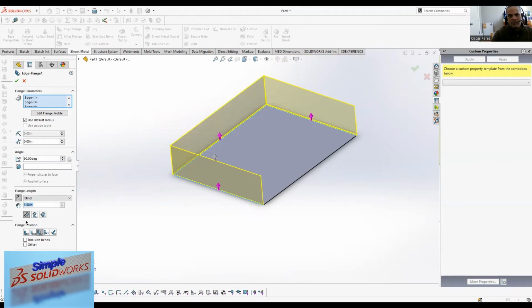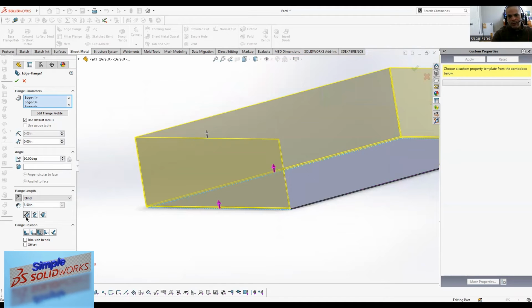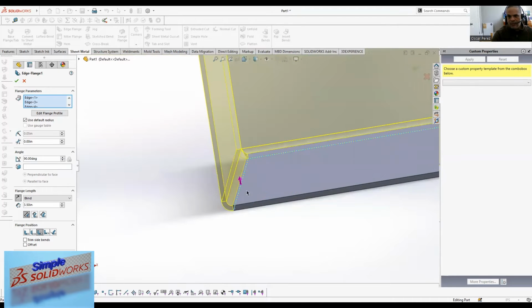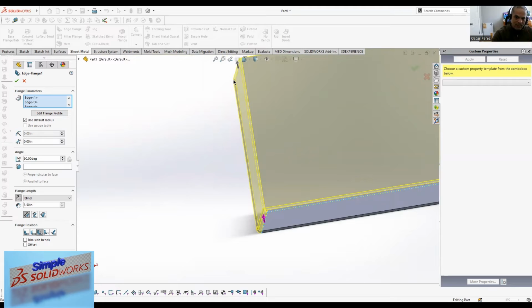And here is where it's important. See these little icons here? These tell it where it is going to be measuring to. Like, what is the distance between this flange and the part itself? Currently, it's going to what is called an imaginary intersection, meaning it's taking the measurement of this flange from an imaginary spot, around there. It's taking 350 from this imaginary spot up here, but physically it might not be 350.